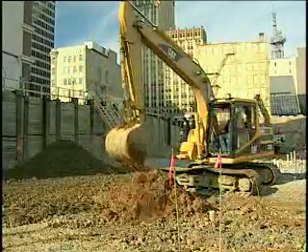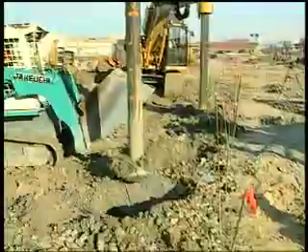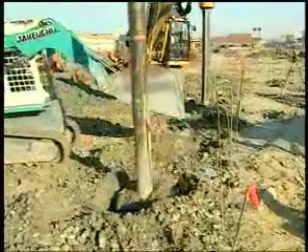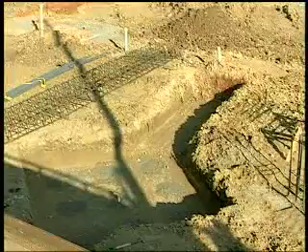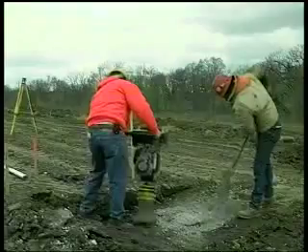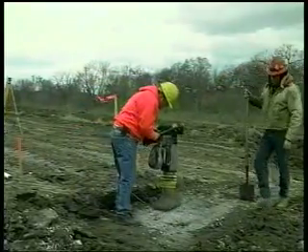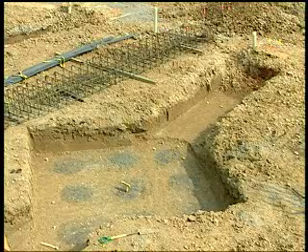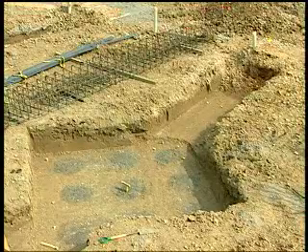For the Geopier system to be fully effective, as with any foundation or ground modification system, the chain of events from design through construction of the supported structure needs to be well controlled. The event interval between completion of pier installation and construction of footings and mats is controlled by the general contractor. This is an important time for proper compaction of tops of piers and footing bottoms, for protecting footing bottoms from becoming water saturated, and for inspecting footing bottoms immediately prior to placing concrete.